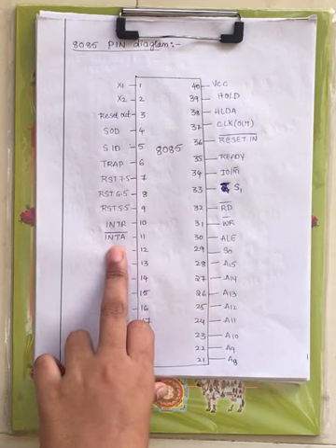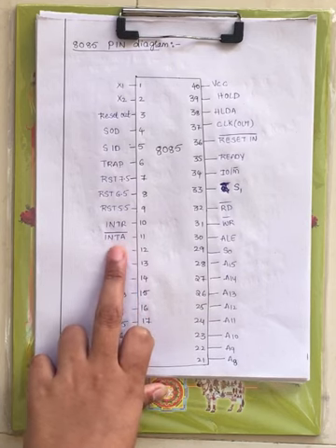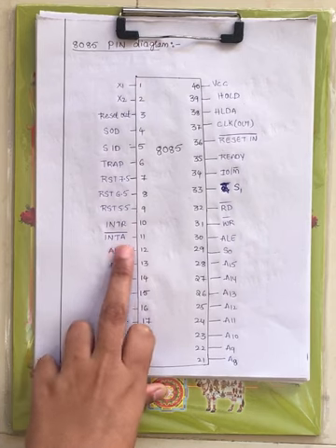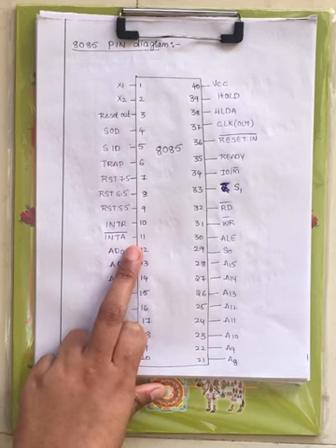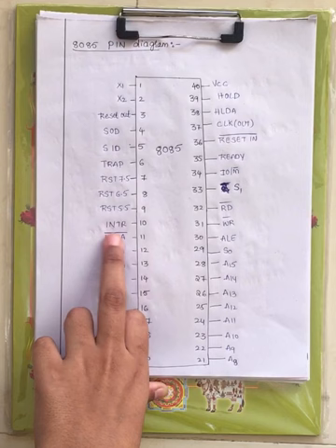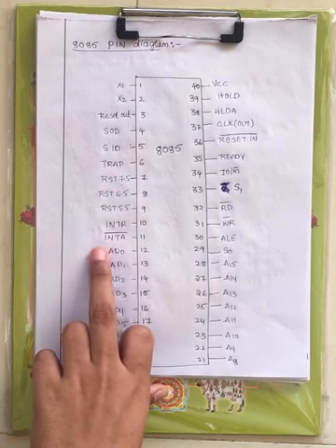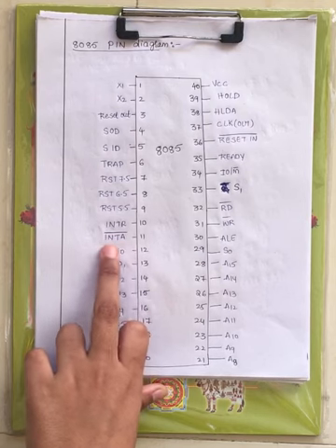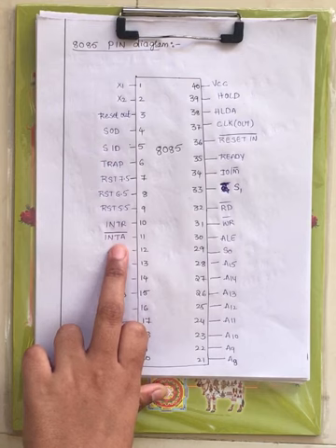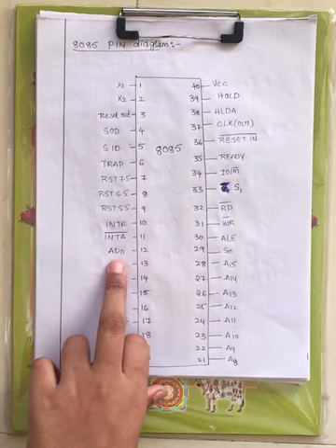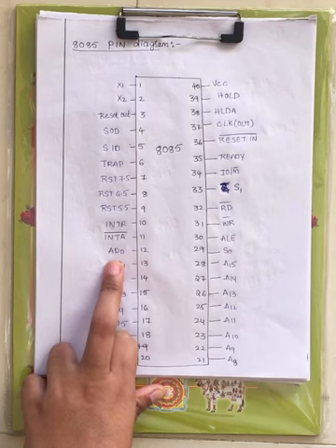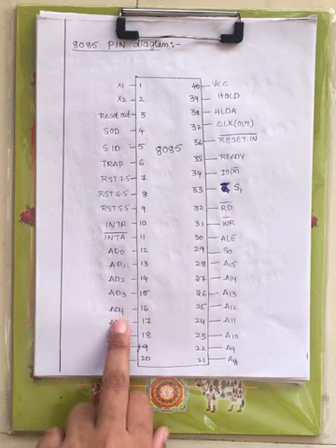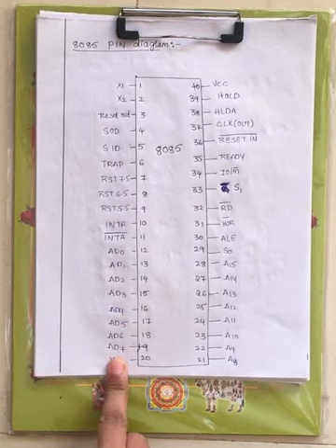And next you have, at the 11th pin, INTA, the interrupt acknowledgement signal. INTA stands for interrupt acknowledgement signal, which is provided at the 11th pin of the 8085. INTA bar is an active low signal. That means for logic 0 this signal will operate, and for logic 1 it won't operate. What its operation is, we will see later. And at the 12th pin, AD0, AD1, AD2, AD3, AD4, and so on up to AD7 at the 19th pin.